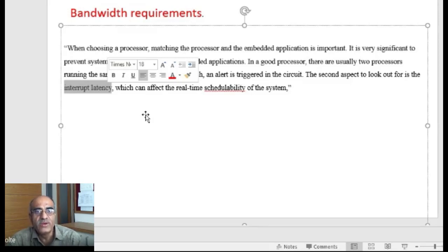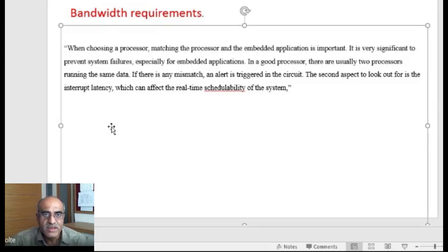Then we should check this whenever we go for any ARM processor. For example, if you go for the ARM7 or 9, a simple interrupt controller is available. But when you go for the ARM9 or 11, we have the vector interrupt controller, which is part of the processor itself. It has its own interrupt structure and interrupt buffers, with the addresses along with the vectors.